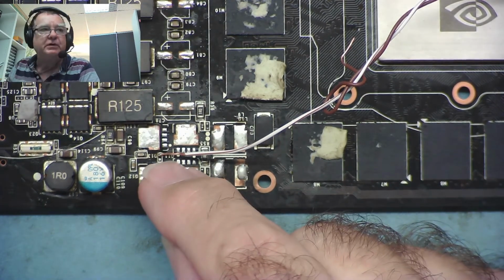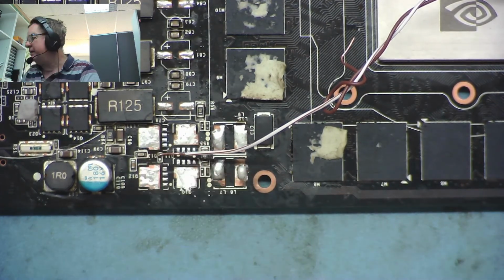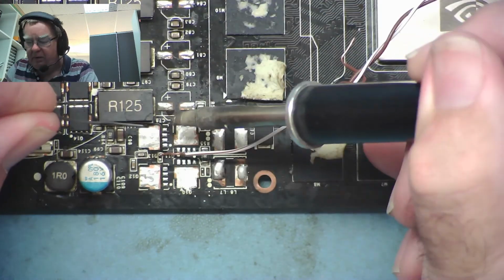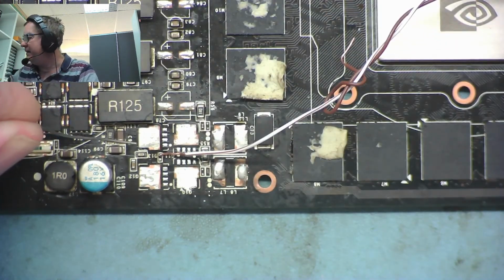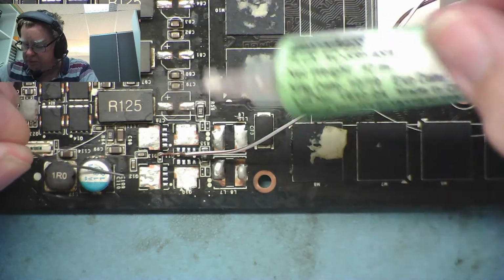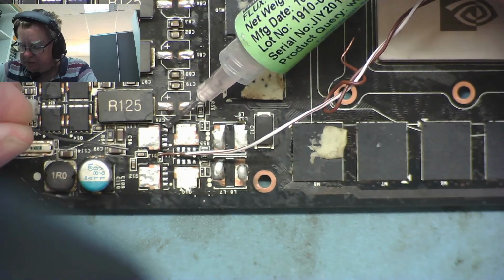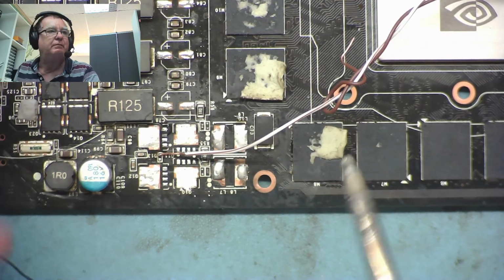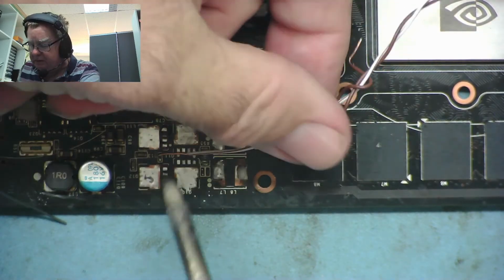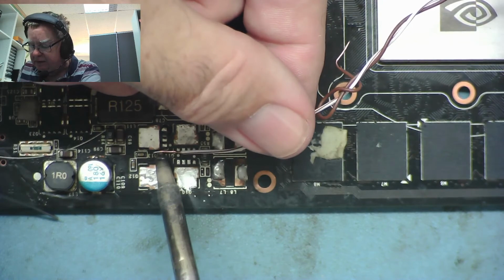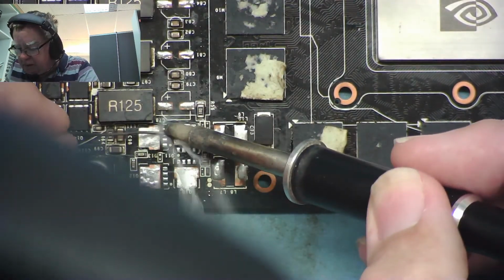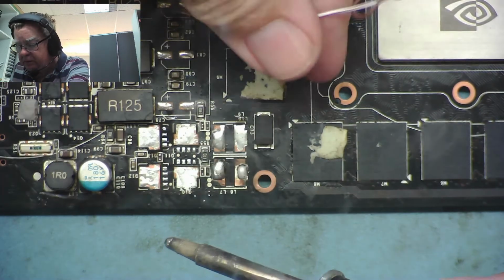So what we're going to do is take this wire off here now and stick it on the gate of the other MOSFET. And I want to see what the resistance is between there and pin 1 on the controller chip. This is on the basis that the two circuits, the two phases, are identical, which we have every reason to believe is the case. So let's take our wire off this pad here. Okay. Let's get onto the gate of the other one. Okay, let's stick it on there.